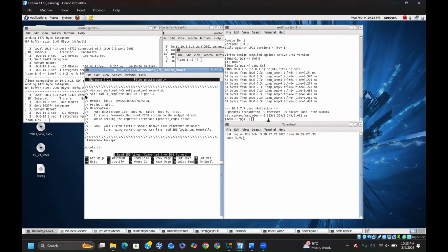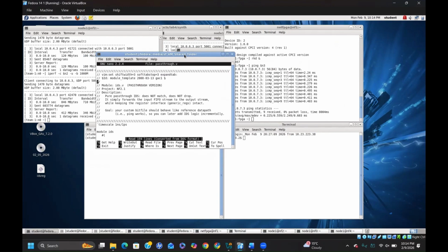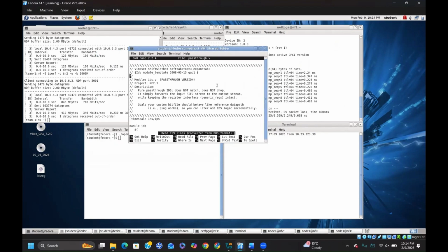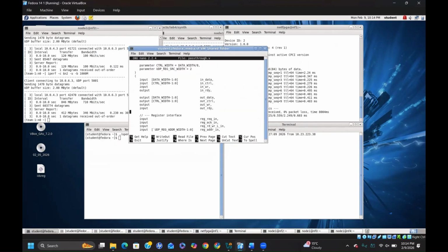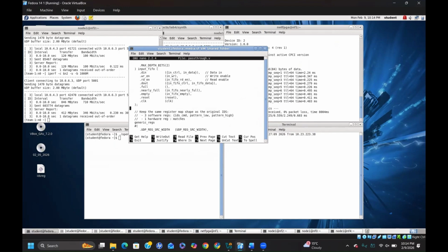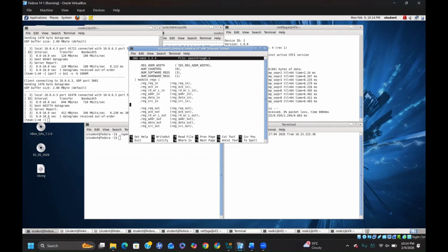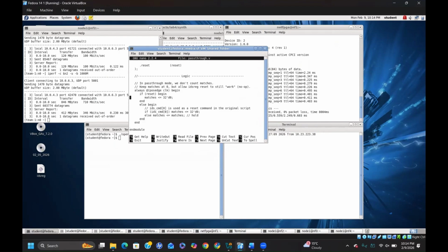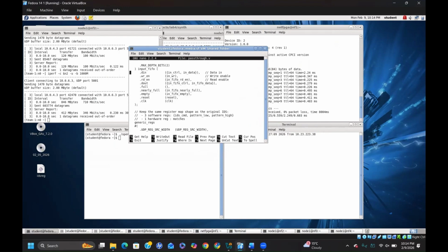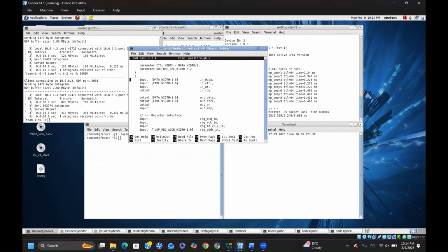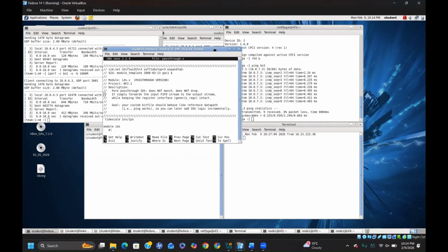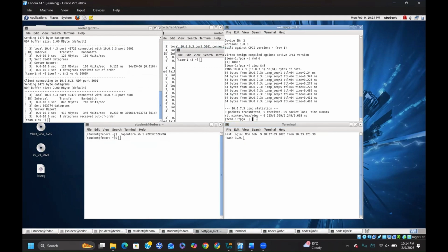So before demonstrating the IDS on the NetFPGA, a pass-through IDS, which is basically a modification. In this, we have removed all of the other modules and replaced them. We just have a fall-through small FIFO here, and in the pass-through, we just have out equal to in in the ids.v, and we have generated a bit stream. So let me try and download this into the NetFPGA.